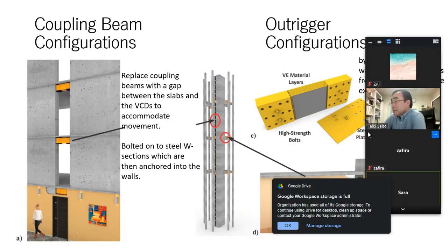And above is the outrigger configuration. This is highly effective for wind application as it reduces the overturning moment and drifts. In seismic application, this system can reduce the drifts and overturning moment, but increases core wall shear and requires careful detailing at the outrigger level.